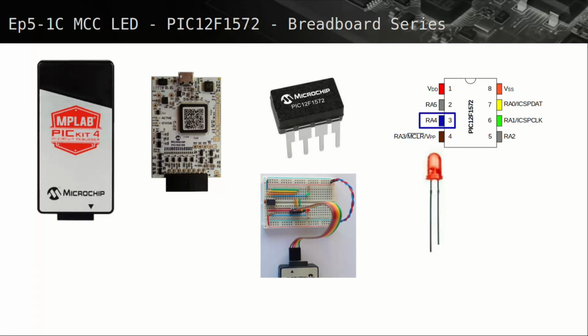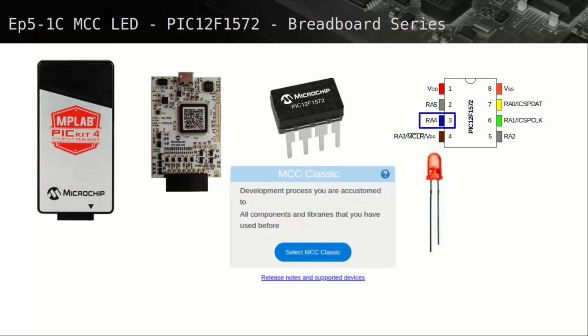The LED will also be moved to pin 3 or RA4 and the required modifications done to turn on the LED here. This will be done in one part using MCC again, and in another part directly edited in previously generated code sections.